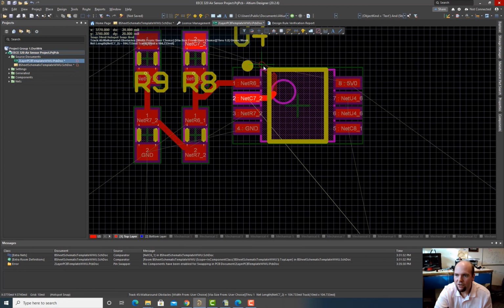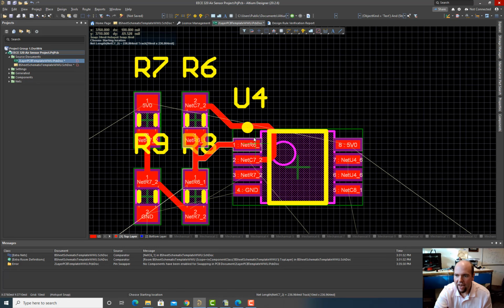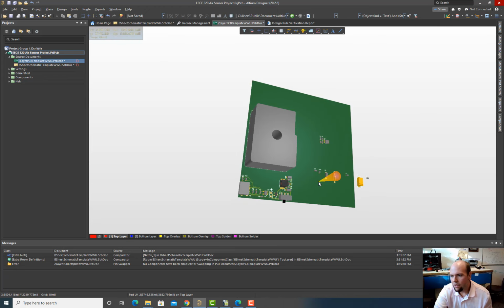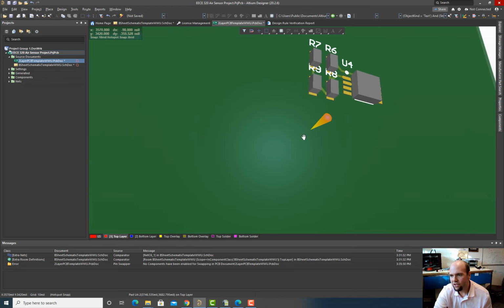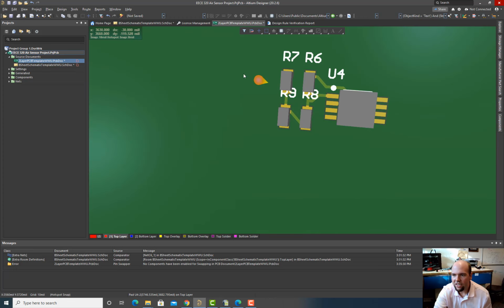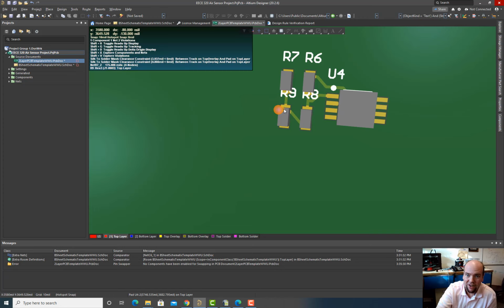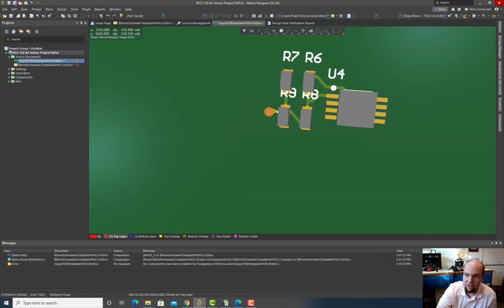So whenever I have wires routed under a chip, I really want to keep them away from those pins, because it is possible to accidentally, if the solder mask is... that's probably something I should talk about. So all this green on this page, this is all solder mask, right? Everything's covered with a mask that solder is afraid of. So solder phobic, right? Solder isn't going to go anywhere where this green is. But wherever you have pads that need to make a solder connection to a chip, you have to have an opening in that solder mask.